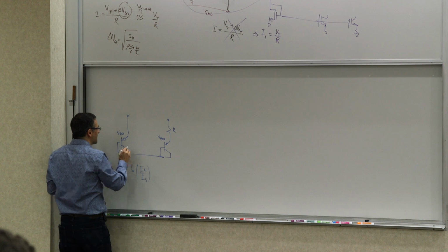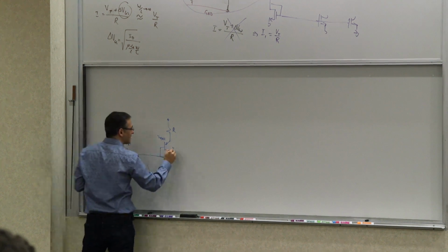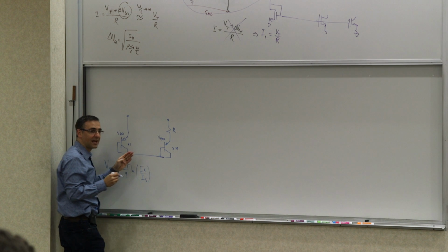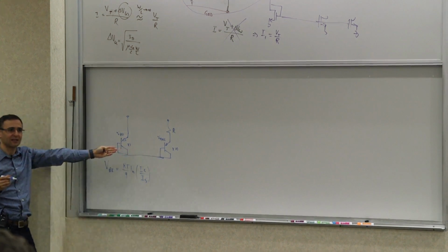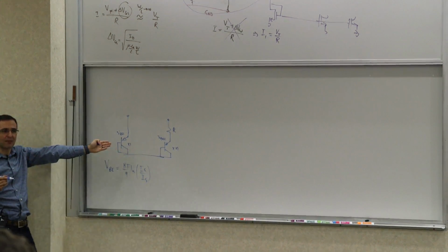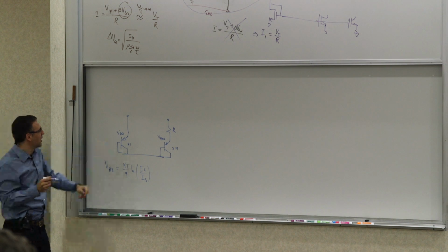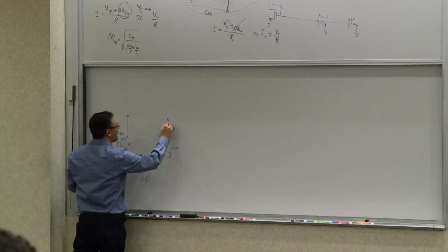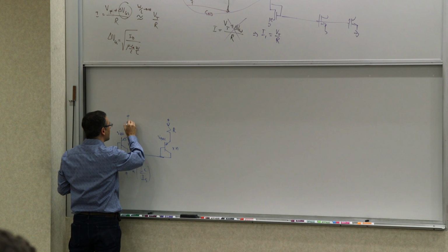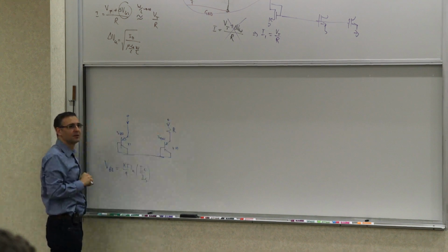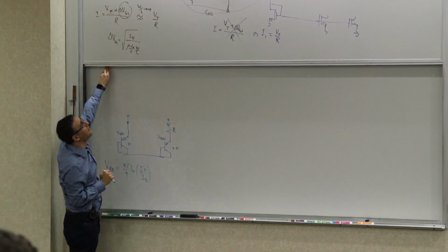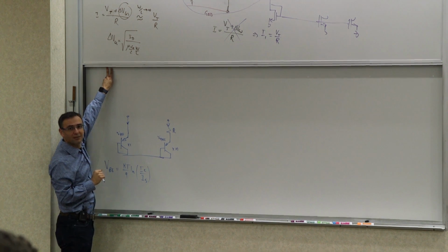And one way to do it is to make this 1x and make this n times larger. So basically make this out of n transistors in parallel, so its IS is n times larger. But it's still the same IS, just n times larger. Can you think of a way of forcing these two currents to be equal and these two voltages to be equal? Well, we just devised the way, right? We called it the floating mirror.